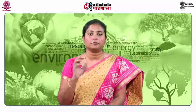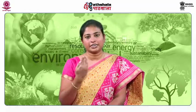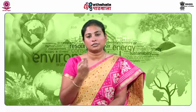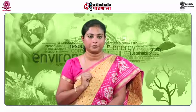Then you should continuously monitor gas flow and quality because when you analyze the quality and quantity of gas generation, that will again indicate the biological activity going on inside the landfill bioreactor, and also this information will be required for expansion of the plan and modification of gas management systems.